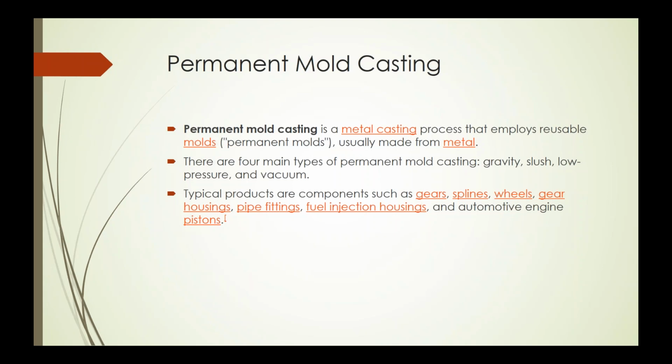You basically produce a mold. It ends up being filled or made out of wax. You make a cast of plaster of Paris or something else around that. And so you end up in that particular type of semi-permanent mold, making a mold, but the wax is still in there. Then you pour molten metal into it, the wax evaporates or leaves, and you have your part.